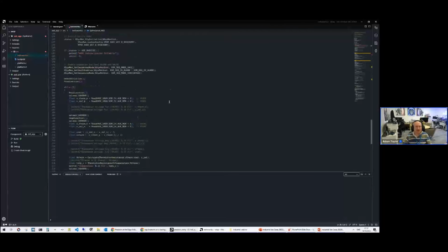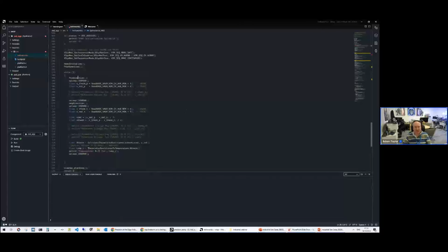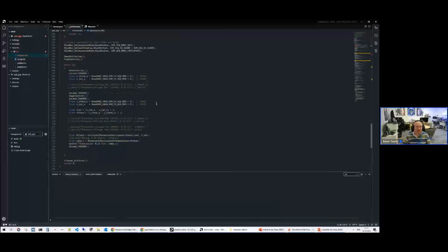Once we've done that, we're just going to have a really simple loop. It's going to set the channels into the positive direction. We're going to sleep for a second to make sure that it's in the right format. Then we're going to do the reading of the auxiliary channel. So we're going to read the auxiliary channel 8, read the auxiliary channel 0, and put those into the thermistor and the reference voltages. If you want, we can then print those out for debugging so we can see where we're going. Then we're going to wait a little longer.